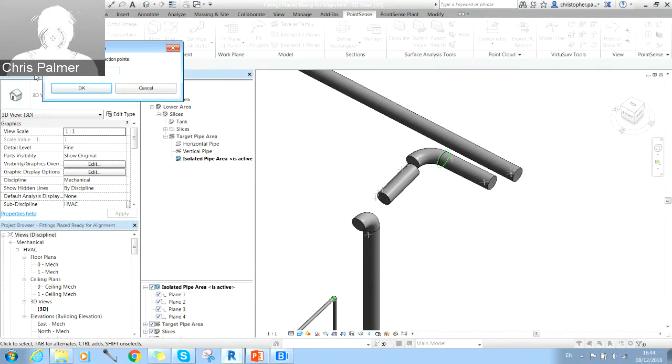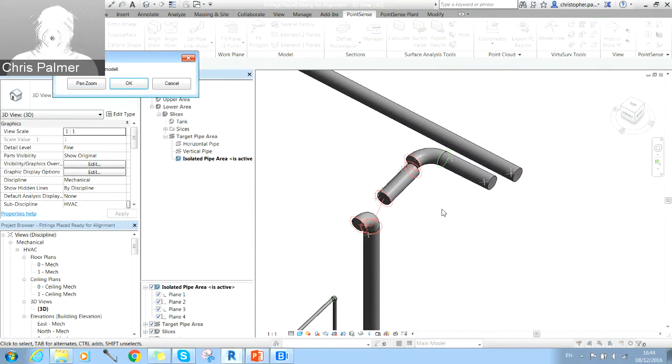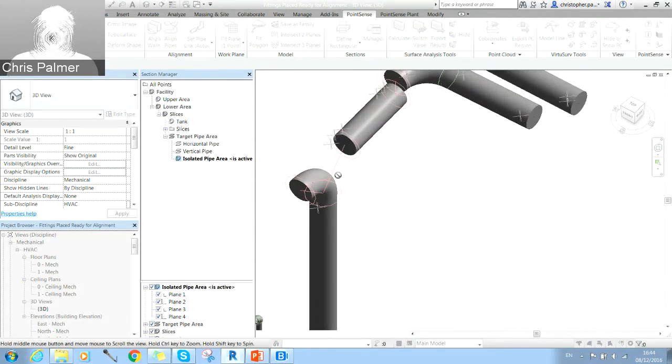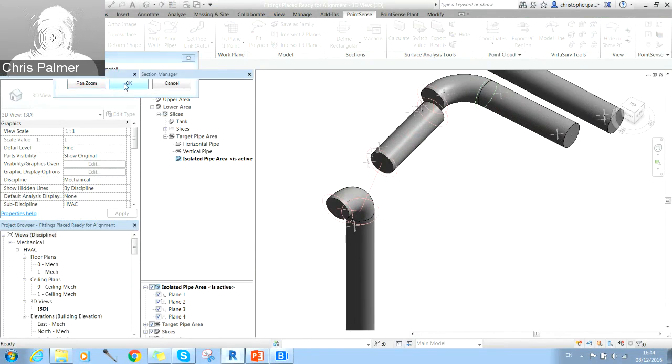So what I'm going to do is run the set pipe link auto tool. And I'm going to give it a nice big search radius of 600 millimeters. If we run this auto link, you'll notice now it finds those additional links between the pipes. It's actually found this one slightly incorrectly, so we'll see what comes from this. But if we go to, oh no, it's just graphical. So let's go and press OK to that.